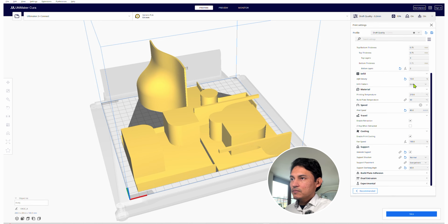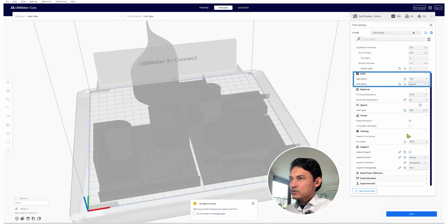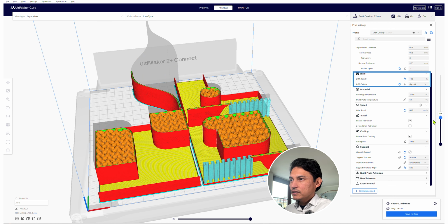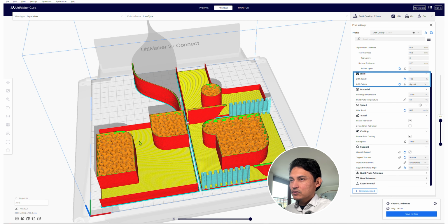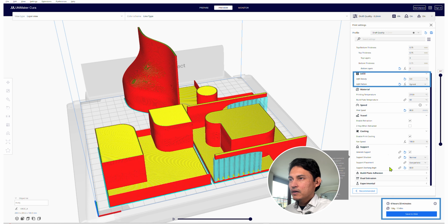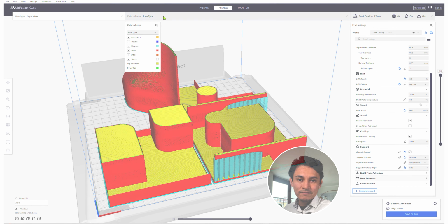First, with the grid and 10% infill, it takes 7 hours 1 minute to print. And now with the gyroid and 10% infill, then it takes 7 hours 2 minutes, almost the same time. But we see here that it's too dense, so the infill can be reduced to 5, or better, let's leave it at 6%, and now we have 6 hours 33 minutes. You see, much less time.